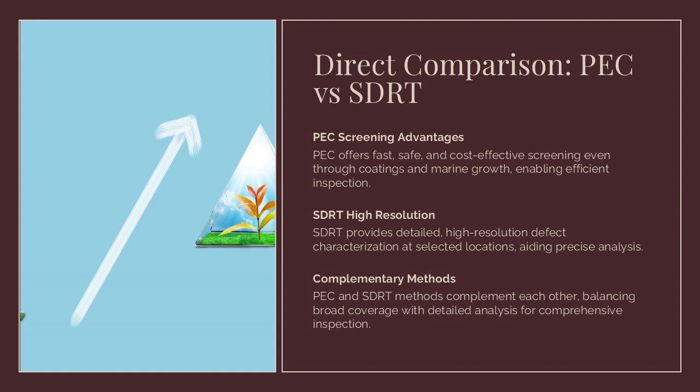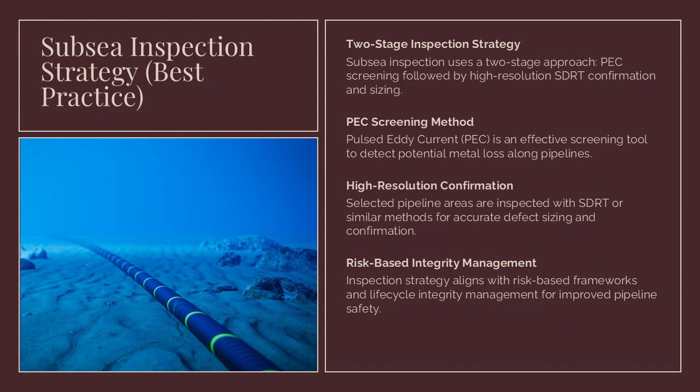PEC provides fast, safe, and cost-effective screening through coatings and marine growth, while SDRT provides high-resolution defect characterization at selected locations. Speaker emphasis should reinforce that the methods are complementary rather than competing.